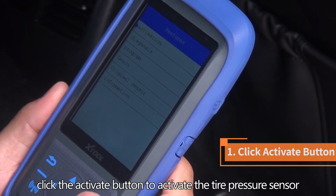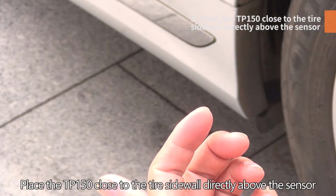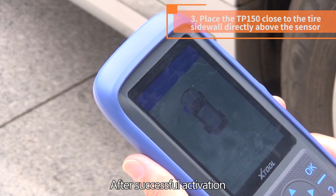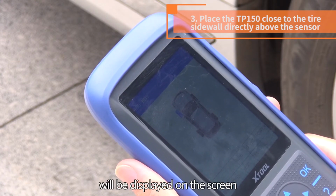Click the Activate button to activate the tire pressure sensor. Use the arrow keys to select different tires, and place the TP150 close to the tire sidewall directly above the sensor. After successful activation, the status and pressure value of the sensor will be displayed on the screen.